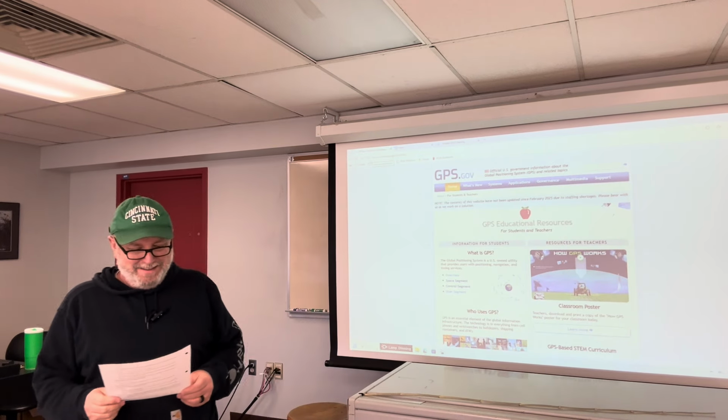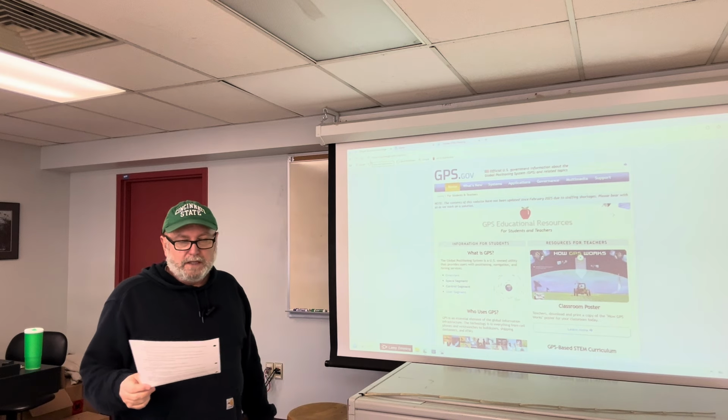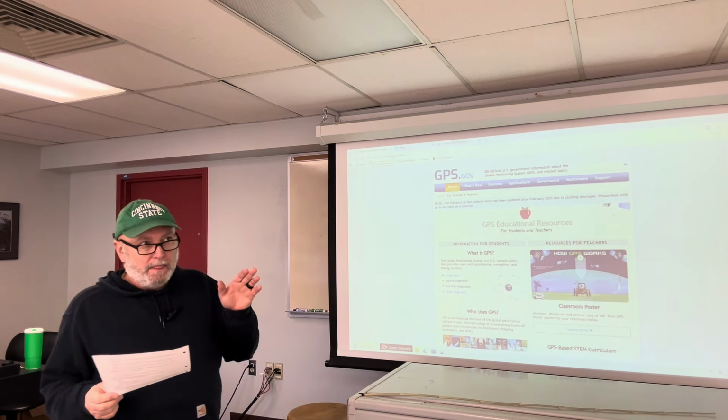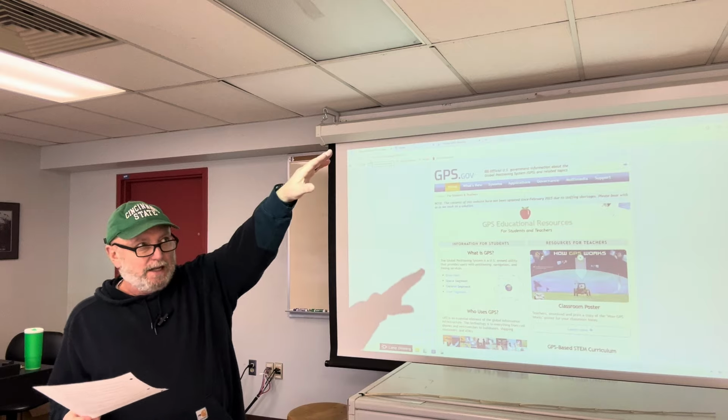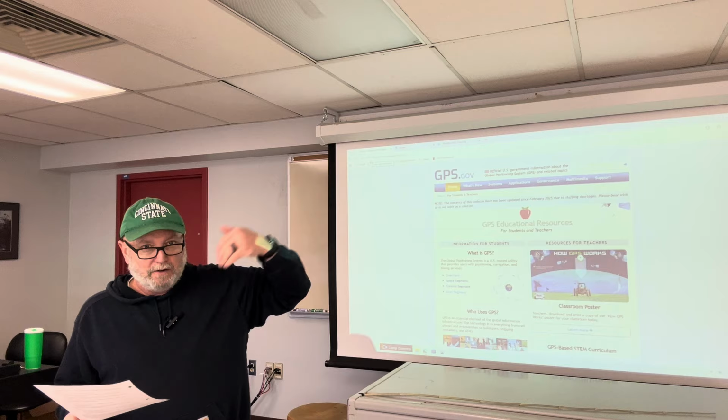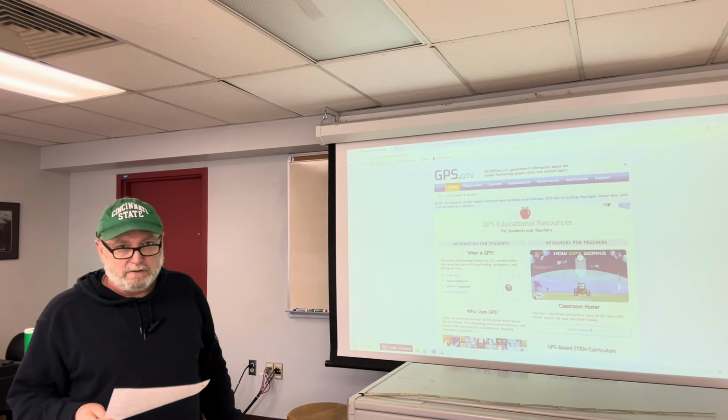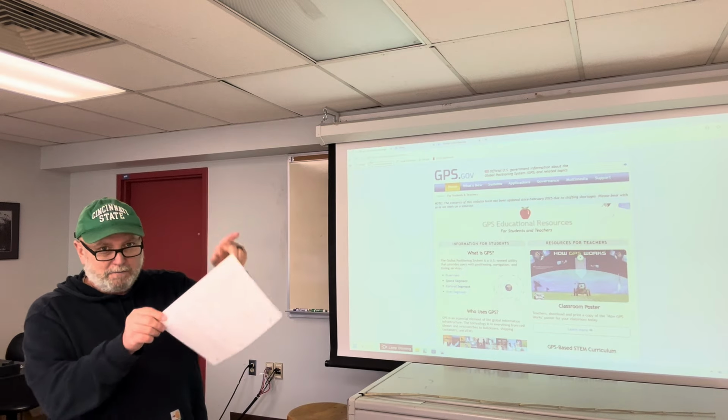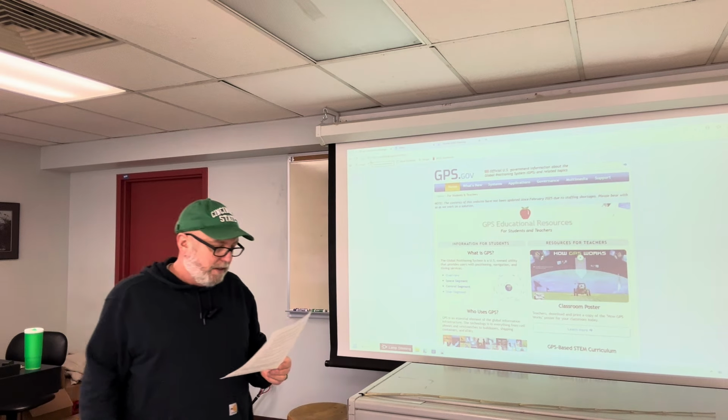So bad geometry examples would be satellites that are bunched in one sector of the sky. So if they're all clustered directly overhead, or directly in front of you in the northern, southern, eastern, western skies, whatnot. Or they're all roughly one-dimensional distributions. So if you have multiple satellites that are all kind of in line with each other, shooting the same signal, you're receiving the same signal, and multiple are in the same line, that would be bad.